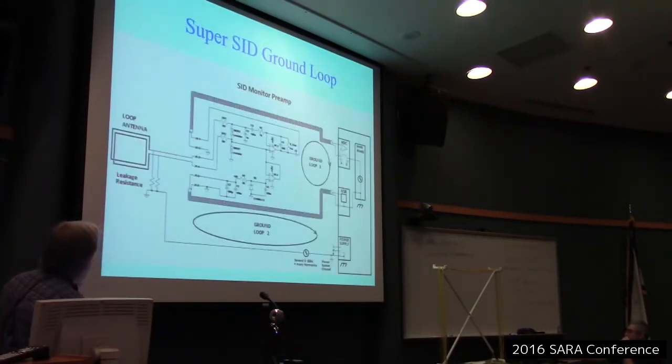And here, looking a little bit at the SuperSID type of thing and some things that can go on with that, sketched out. This is one version. There are several versions of the preamps floating around. I'm not sure what's current now, but they have the thing with USB supplying power for it because they had a problem with the worldwide power supplies. There was a variety of voltages, and finding the right wall wart to ship along with your SID unit was apparently a problem. So it picked up power off the USB.